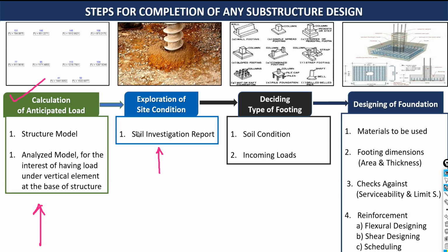Either we go with the pad footing, or the raft foundation, or the pile foundation. Which type of foundation we choose for our structure mainly depends on the soil investigation report. And what kind of substructure you have to take is also given by your soil investigation report.